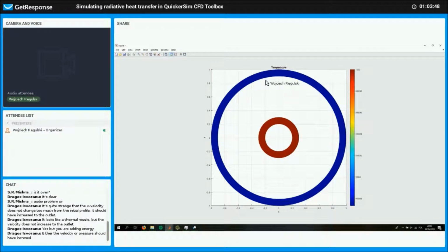So in the next iteration, this one would be very cold and this one would be very warm, colder and warmer than in the previous iteration, and this would oscillate back and forth, and the temperature amplitude would increase. It would just blow up, and we wouldn't get convergence. So once again, what you need to do is employ under relaxation.